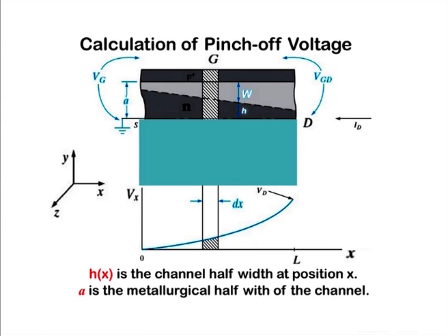The source is at reference and we apply some voltage Vd at the drain, so this increases linearly. We can take one small slice, where the width of the slice is del x, at position x and x plus del x.